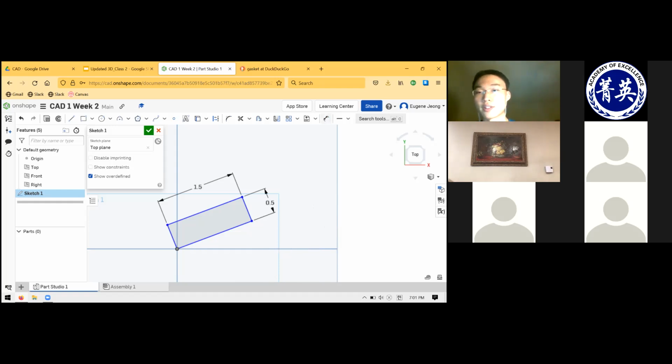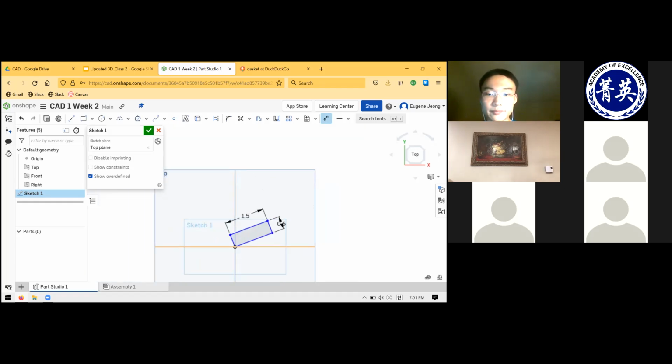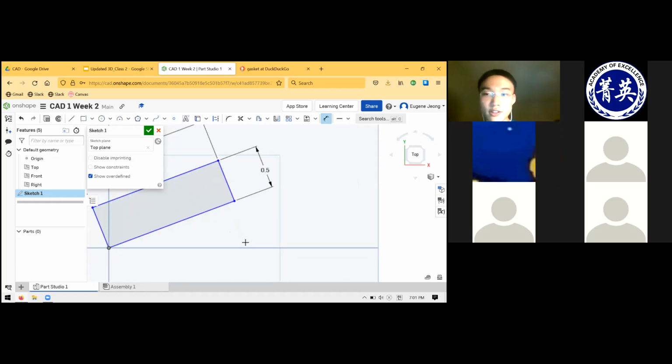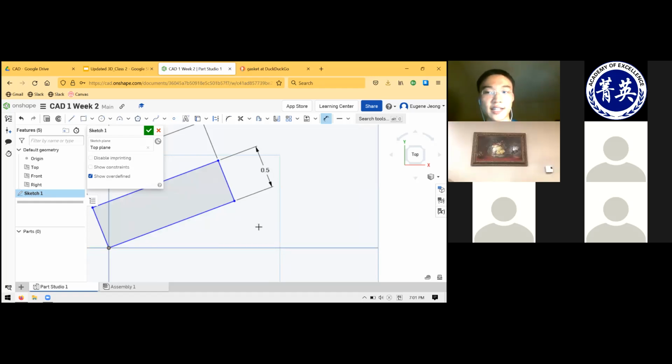But for now, using the dimension tool, you should just be able to select, in this case, the x-axis. So you can see I can use things that aren't even part of my sketch that I didn't explicitly create. Like I didn't draw a line that is the horizontal axis, but I can actually just select by default what is the front plane, I believe.